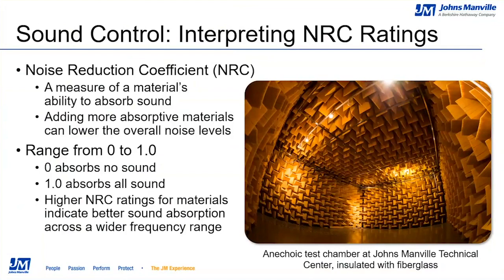I should mention here that architects or designers may work with STC, or Sound Transmission Class ratings. STC ratings refer to how well a building partition prevents sound from traveling between rooms. It measures the reduction in noise between 2 rooms in decibels. One of the most important distinctions of an STC rating is that it measures the acoustical performance of the entire wall or floor system, the studs, the drywall, and the insulation as a whole, not just its individual components.